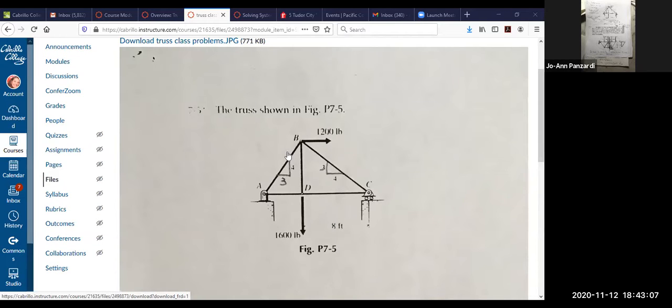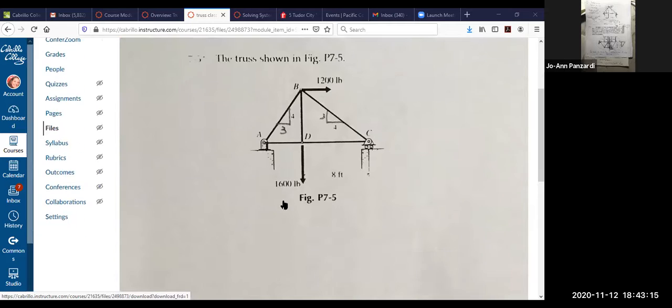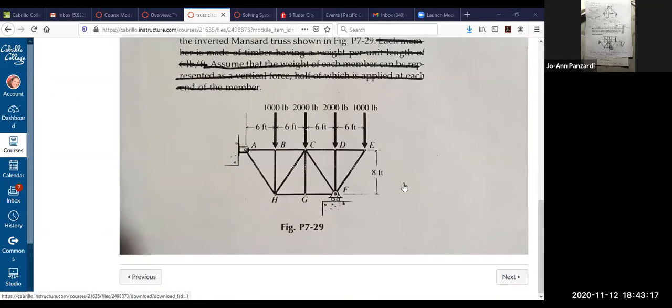This truss I picked is small. There are only 5 members and only 4 joints. It wasn't that intense. But imagine doing this problem with method of joints. 1, 2, 3, 4, 5, 6, 7, possibly 8 free body diagrams you would need. So you could see why I like method of sections better.